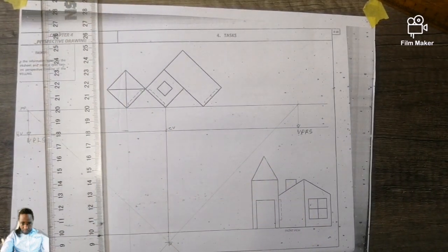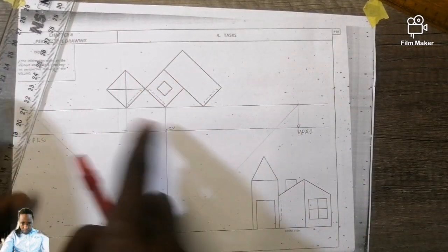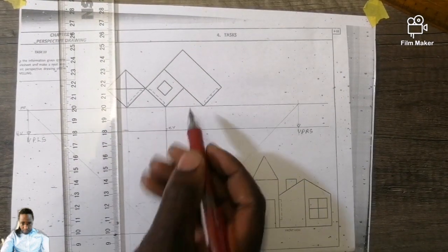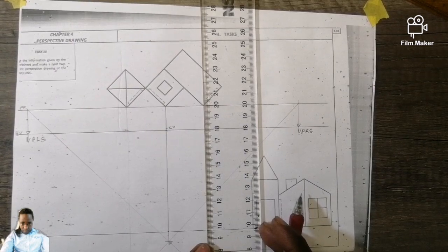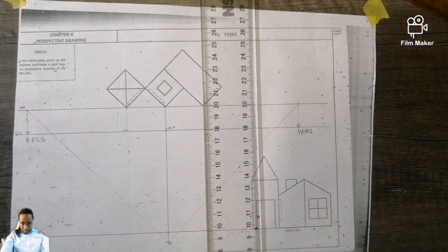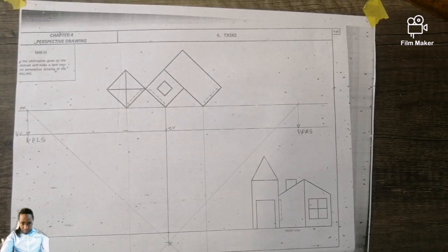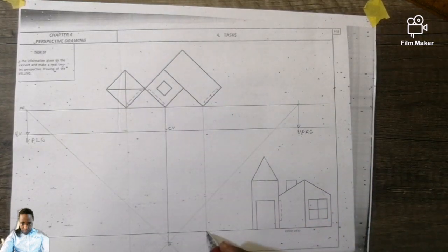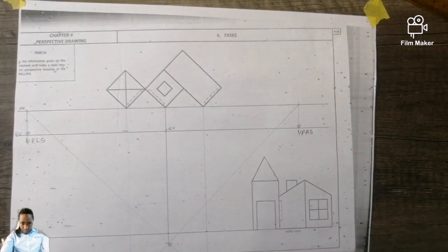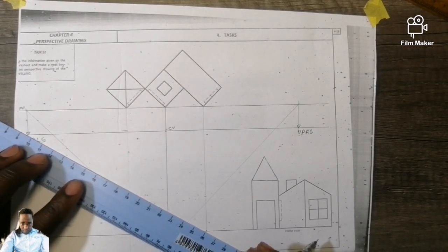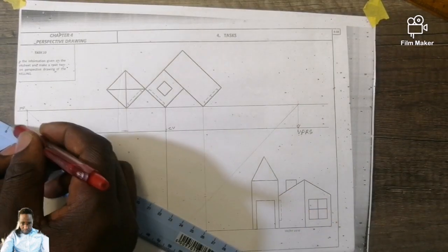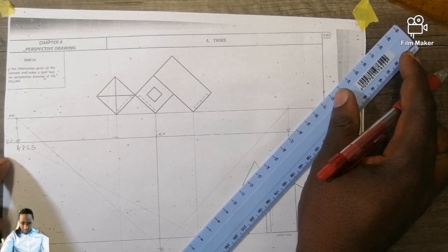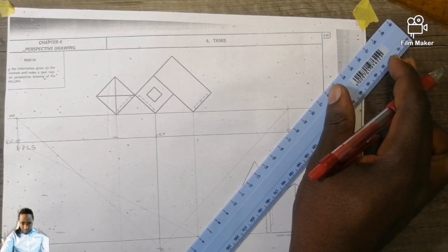this vertically down, because the law says all the points from the top view, once they touch the picture plane, they become vertically down. So these ones, 1, 2, 3, they're actually already touching your stationary point, so they'll automatically go vertically down. You understand? So now we are going to start with this one. So take this point to the vanishing point of your left hand side. This is an interesting drawing. So take it to the vanishing point of your right hand side as well. Left hand side, right hand side. There you go.